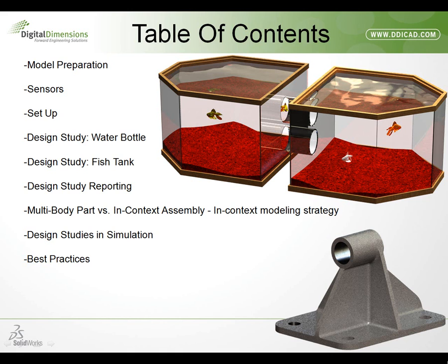And part of that design intent would be what I call model preparation. And with that are things like renaming features and dimensions so that when I go to assign equations to dial in my design intent, equations are relationships between your dimensions, you'll understand what the equation editor is actually doing based on the name of those dimensions.